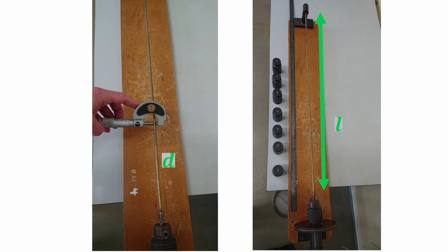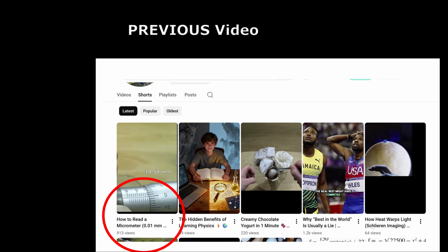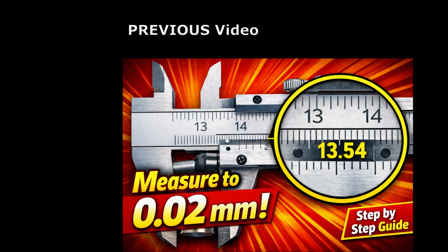We need to measure the diameter of the rod using a micrometer and the length of the rod using a metric ruler. We measure the lever arm of the effective gravitational force using a vernier caliper as the difference between half of the outer diameter of the pulley and the depth of the pulley groove. If you don't know how to use a micrometer or a vernier caliper, watch my videos titled How to Read a Micrometer, 0.01 millimeter precision, explained in 58 seconds, and How to Read a Vernier Caliper, 0.02 millimeter accuracy explained.